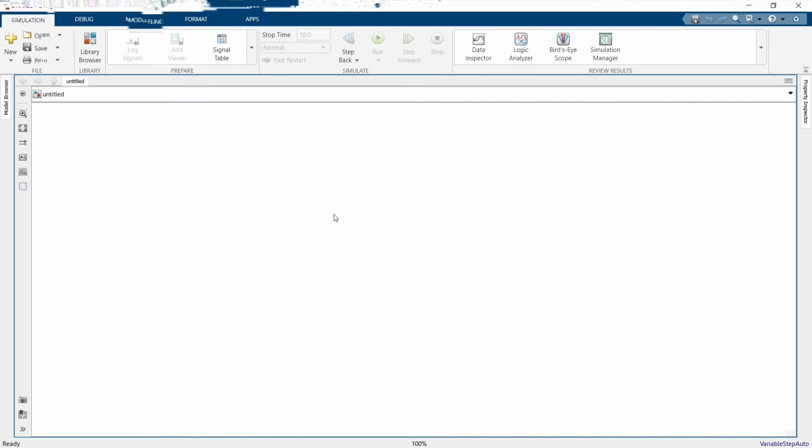So I'll just use a previously modeled algorithm. This algorithm will provide me my Vref and Iref values. I'll just connect them to my Vref and Iref values. Then the SD value is the signal that will be provided as an output. This signal is used to switch on our IGBTs.